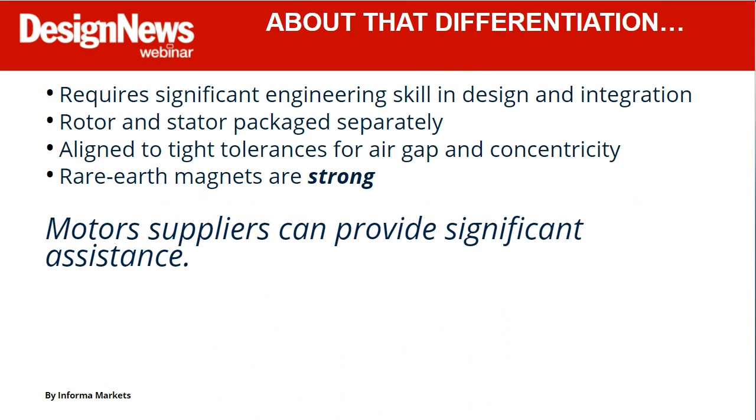But the thing to bear in mind is they don't come nicely housed and ready to install. They come packaged separately, and you've got to have the skill sets to be able to align to the tolerances for air gap and concentricity.